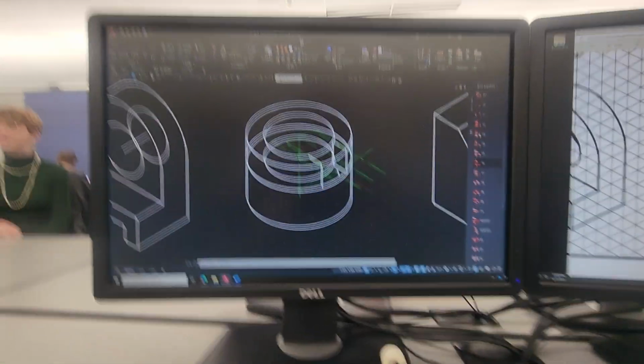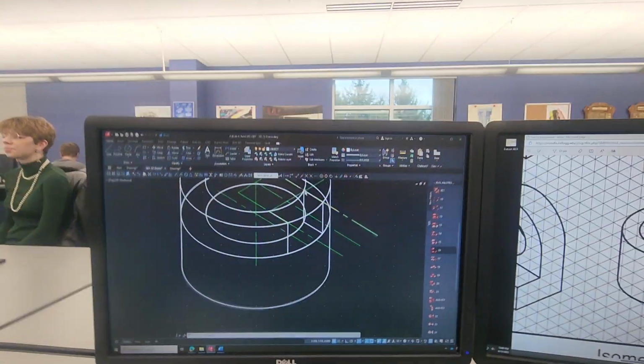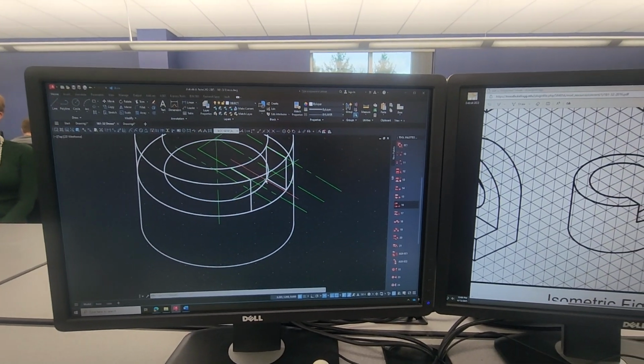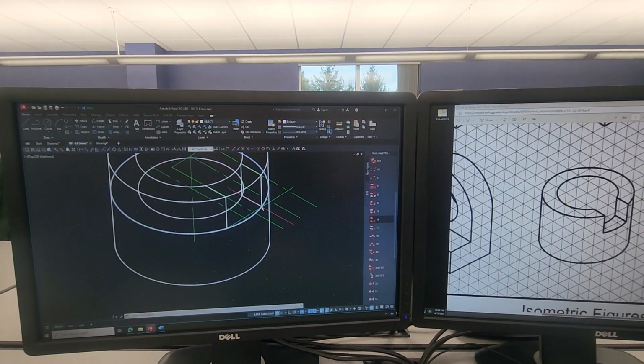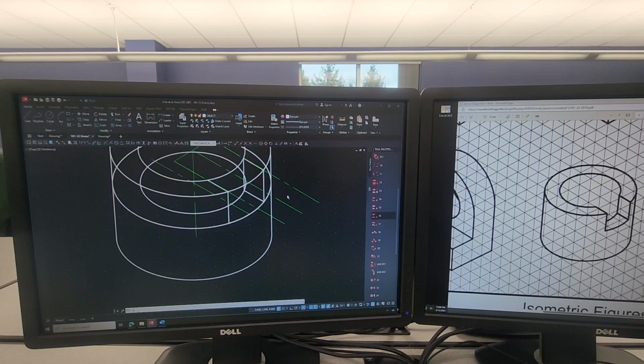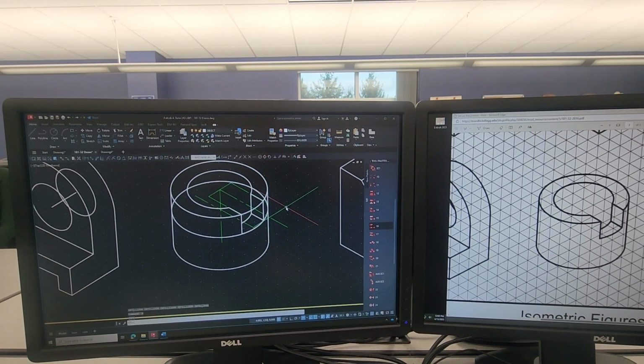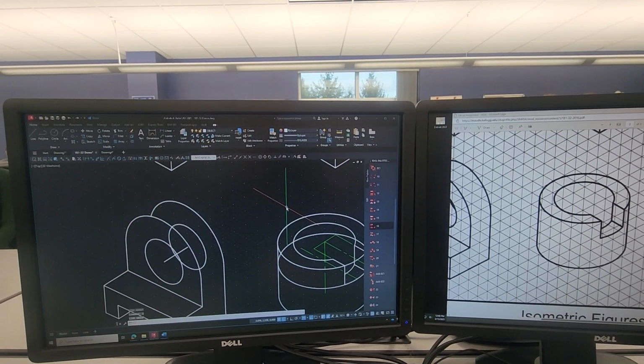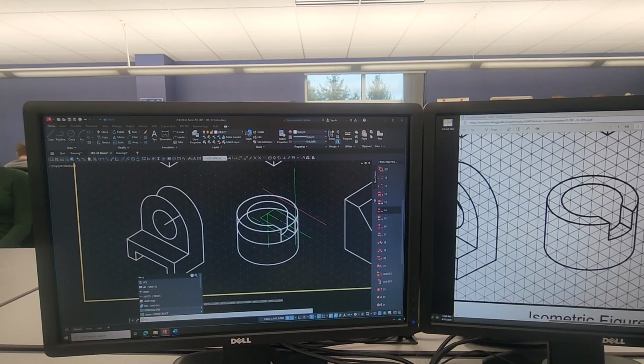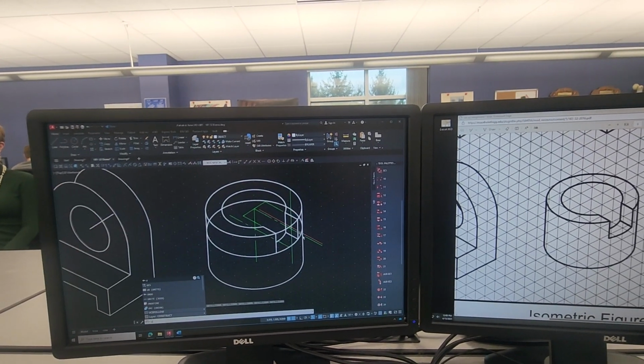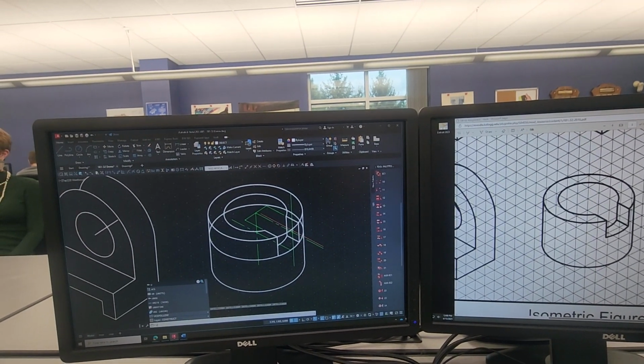And that's how we get that. And then, of course, I can draw a line down from there where it intersects that circle, and where I draw a line down there where it intersects the circle, is where I will leave the geometry that I need in order to show that particular feature, and the back over here at least, this guy right over here, so that's what I'm looking for. So the rest of the stuff can be trimmed out to give me what I'm looking for right here.